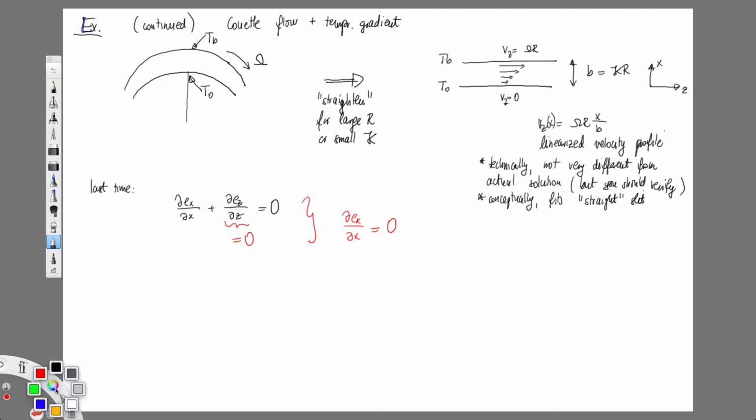Now what is my Ex? It is the x component of that combined energy flux vector. First we have the convective part that moves into my control volume, carrying in kinetic energy plus internal energy, and there was that combination where I split the energy and I'm writing it in terms of enthalpy here.